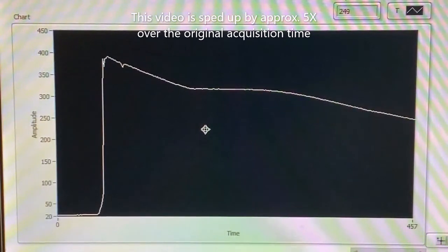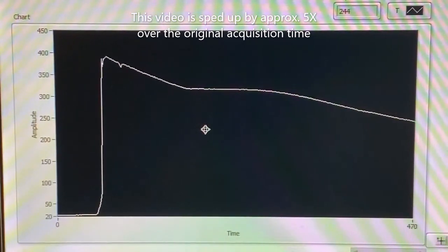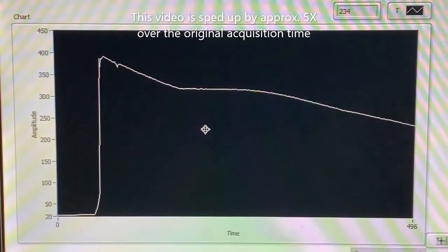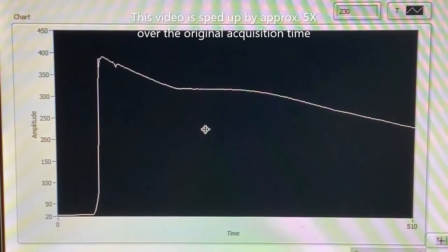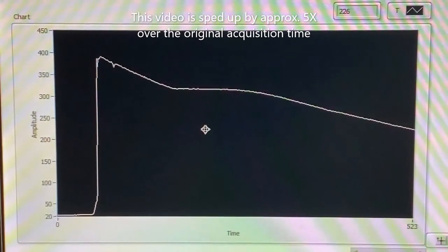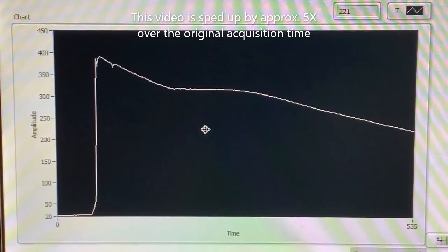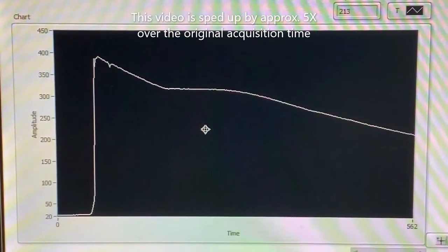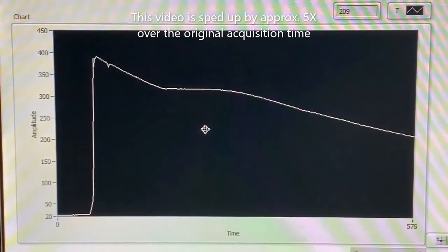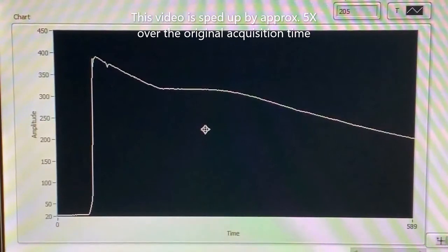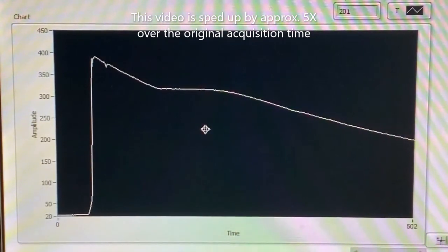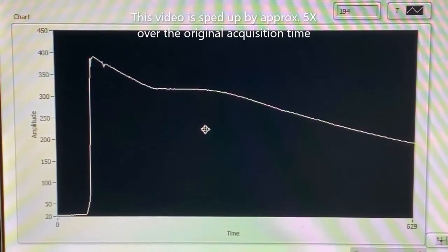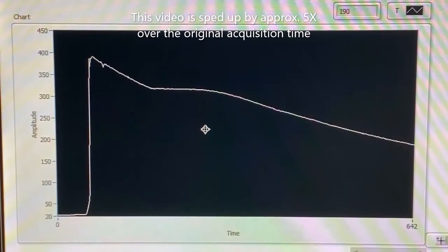The cooling of the solid then follows, and as you note, there's again a downward sloped curve. It's now more gradual than the cooling of the liquid because the solid itself cools more slowly than the liquid. Assessing the entire curve, it now consists of an initial downward negative slope of the cooling of the liquid, a short horizontal isotherm associated with the liberation of the heat of fusion, and then a downward slope of the cooling curve of the solid. And the cooling of the solid would continue along a similar slope until it reaches room temperature.